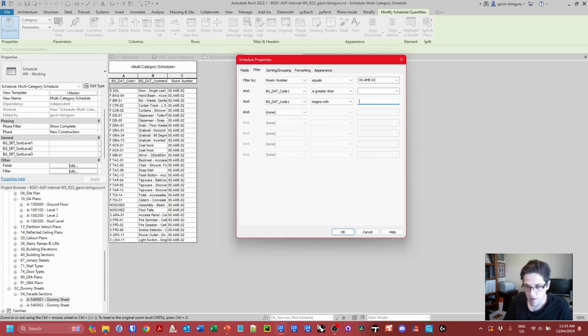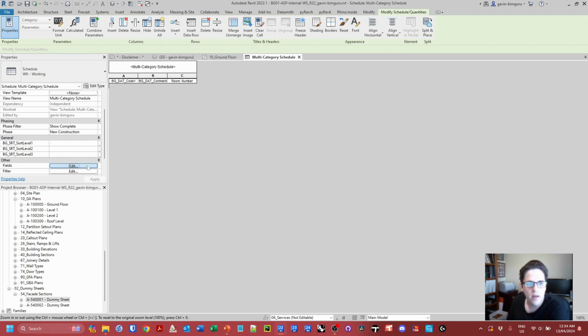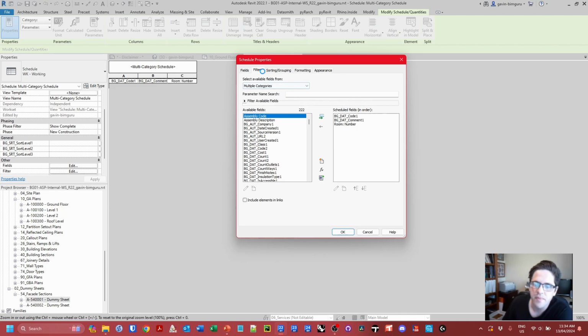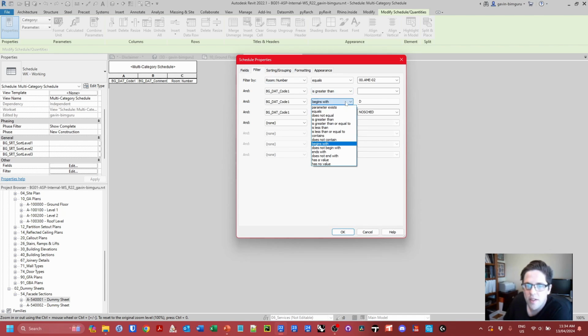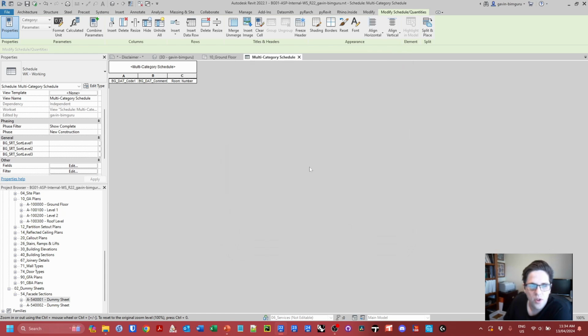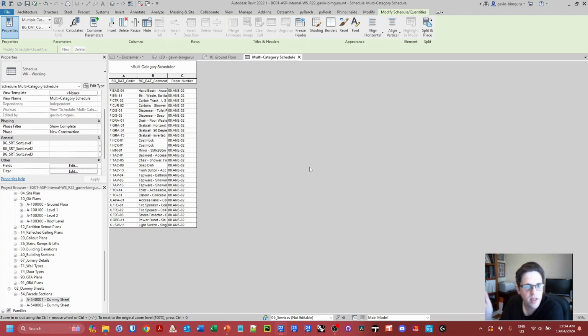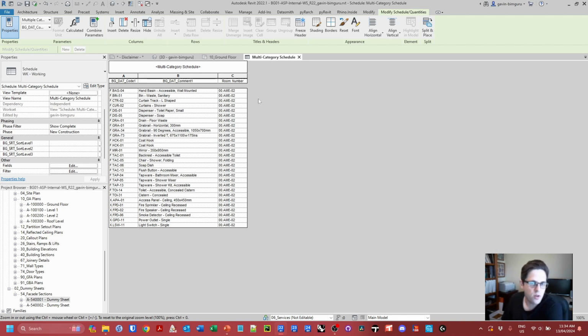D dot. I could also just do D, actually, and I might just do that. And also we're going to hide anything whose code equals no schedule. And there it is. I've obviously filtered a little bit too heavily there. So in this case, we want to say does not begin with, my bad, and does not equal. So I wasn't too careful there. There we go. And now we're just left with the things that we care about. So if I just make this a little bit bigger, we're now starting to look at an equipment list.